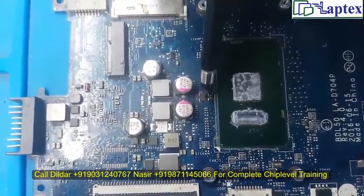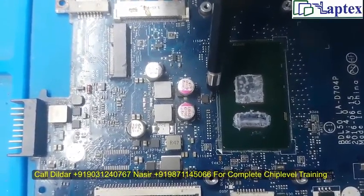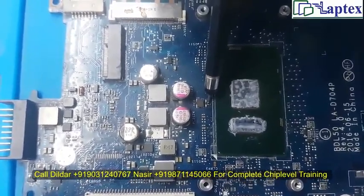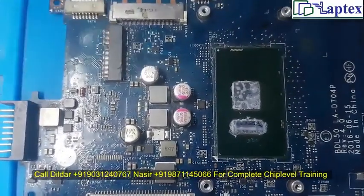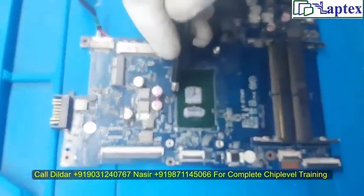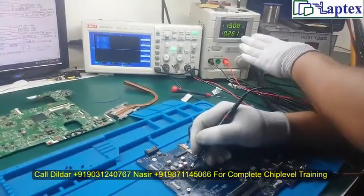Before going out, you will see that it is connected with a high value of pF, and there would also be a 10 mega ohm resistor, the highest value you can see nearby the crystal. The 10 mega ohm resistor would be there. Now my motherboard is on, as you can see.